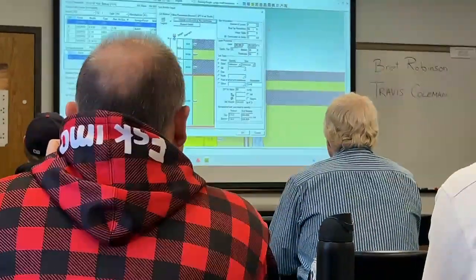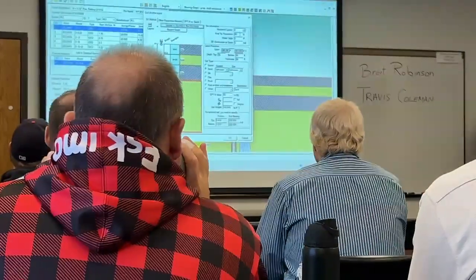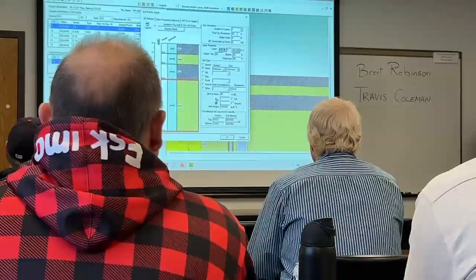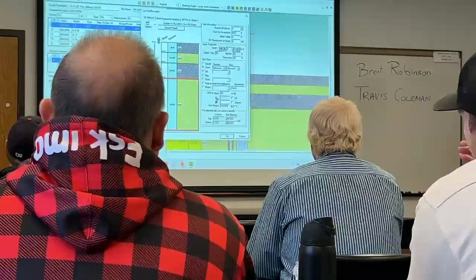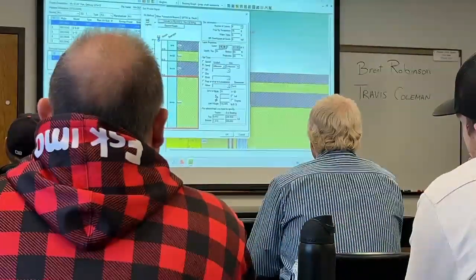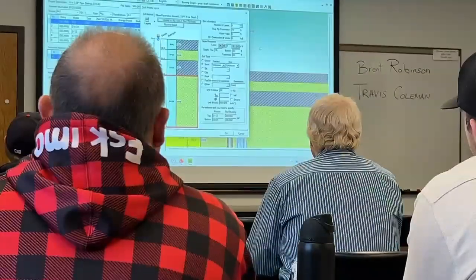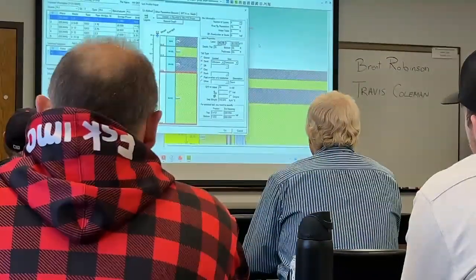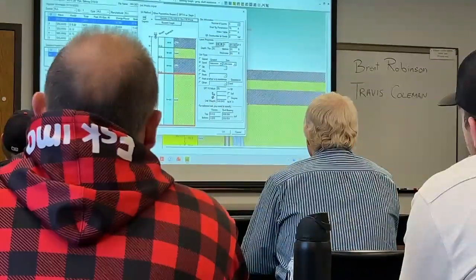So that's basically my static analysis, which I could have just done by hand or on paper, says that I need to go 80 feet in the ground to achieve the 400 kips. So curious, let's say I have 400. So 402 kips. So now I've got it dialed as close as I can to that required capacity. So 79 feet in the ground.